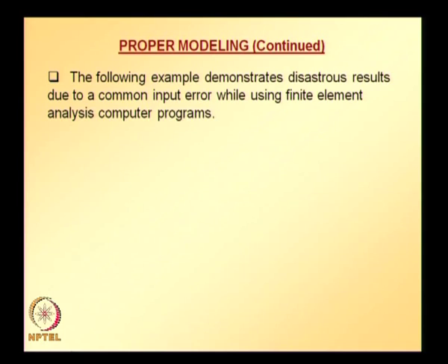The following example demonstrates disastrous results due to a common input error while using finite element analysis computer programs. Sometimes if we violate the node numbering, for the 2 dimensional case either all the nodes should be numbered in clockwise direction or anti-clockwise direction, some problem with results may arise.